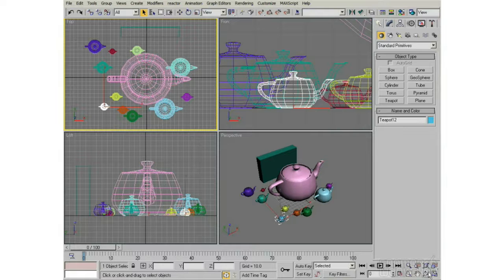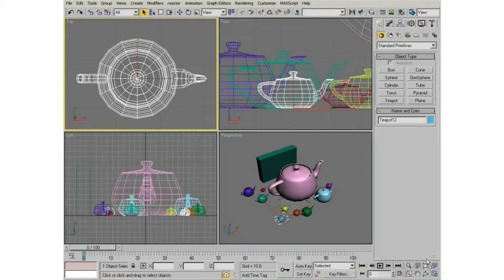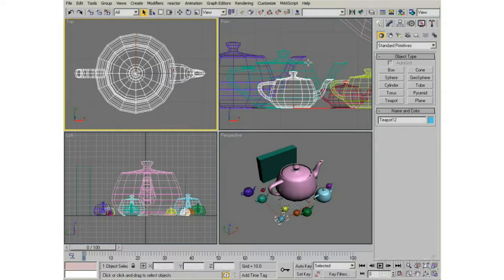Now, that Zoom Extents button has a little tiny black triangle in the corner of it, which means that it's a flyout, which means that if I hold it down, it will give me access to similar, but slightly different tools. So right now, if I'm in Zoom Extents, if I hit this one, that's zoom to selected in the current view. So there's Zoom Extents and Zoom Selected. What that does is, whatever I have picked, it will in the current view zoom to that.